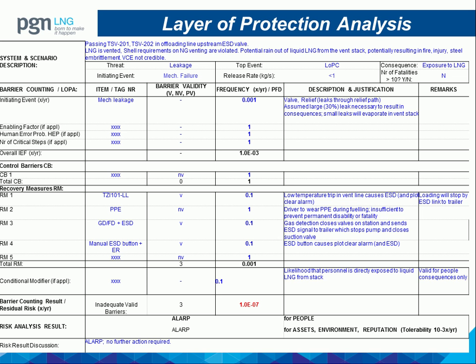It will be like another 2 days to explain about LOPA, but you get some view basically from this. The initiating event we would put as a frequency, and then every mitigation we will put as whether the barrier is valid or not, and then what is the failure rate of the barrier, and then at the end whether the residual risk is okay or not.